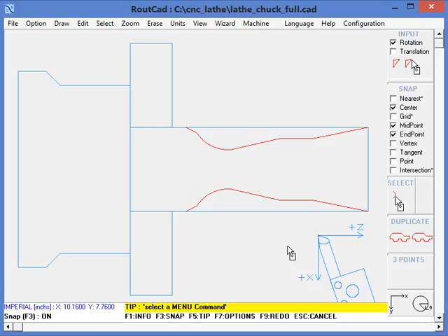The first thing we have is a point. We can see that small x is a point that is at the origin, and in this case, we made that point represent the same place that will be the home location on a CNC machine. So basically, we draw this blue construction element to represent how our CNC machine is set up, and this point represents the 0,0 location on our CNC machine.